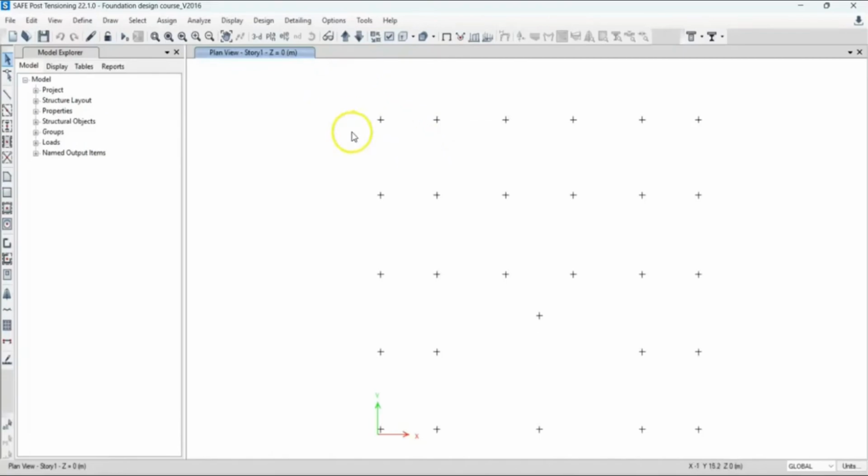That is, we are going to have individual footing for every column point, right? If any footing is overlapping, then we can design that particular footing as a combined footing. For a start, we are going with isolated footing because this is just a 2-story residential structure.